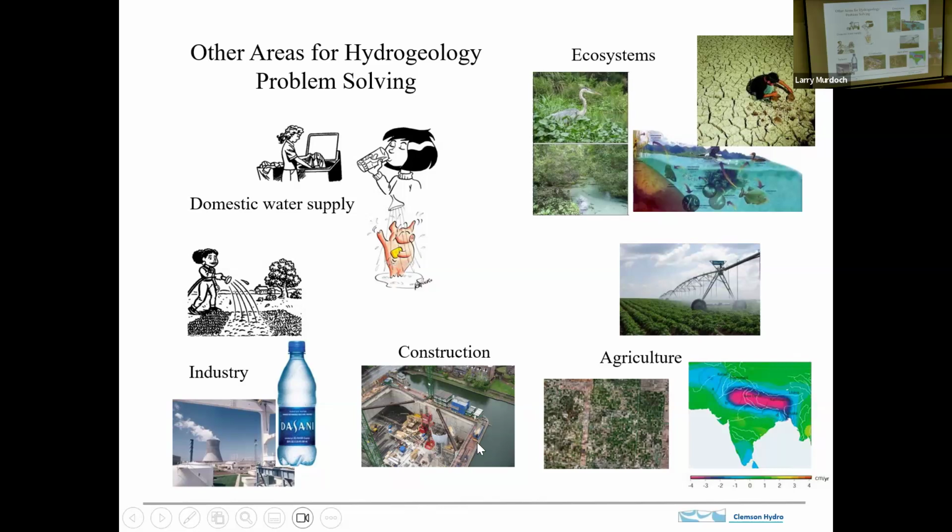Sure. There are a lot of applications. Agriculture needs water for irrigation all through the Midwest. I don't know if you can see, this is really small, but there are lots of green circles here. Maybe in the front row you can see these green circles. These are from center pivot irrigation systems, where at the center of that circle is a large capacity groundwater well. Typically the way it's done is to pump the water out of that central pivot location and then spread it out. And it allows you to grow crops in areas where the water supply is low.